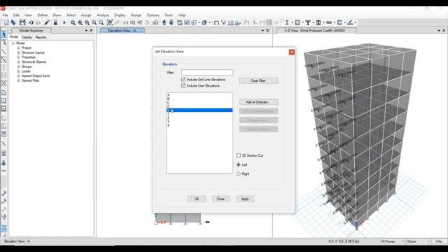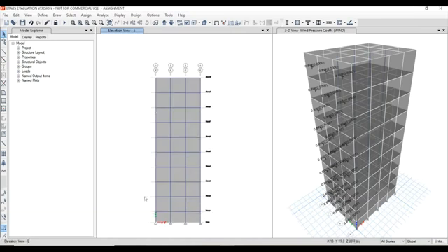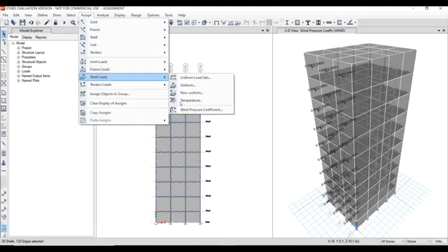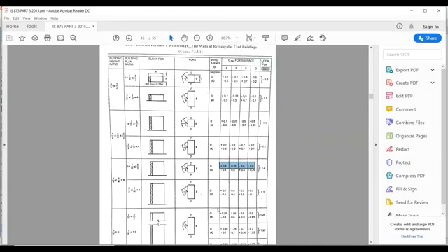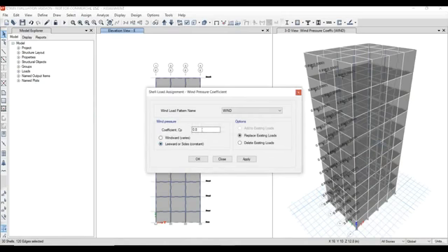Now we need to select the last elevation so that the wind will be facing the last face. This is elevation E. So make sure that all stories are selected. Select every story shell. Now assign the load. Assign shell load wind pressure coefficient, which we already got, minus 0.25 in leeward direction. Click leeward, minus 0.25. Apply.